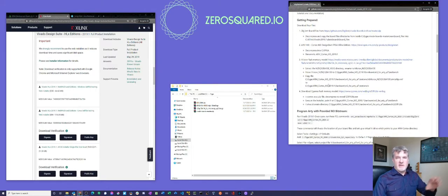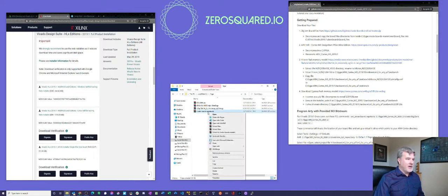I already have them in this directory here in the middle, but you will want to download the Digilent board files. Just paste this link into your web browser and it should download it and should show up as this Vivado boards master.zip archive.